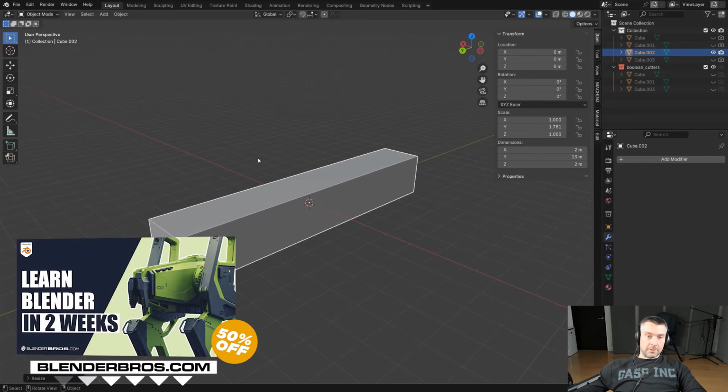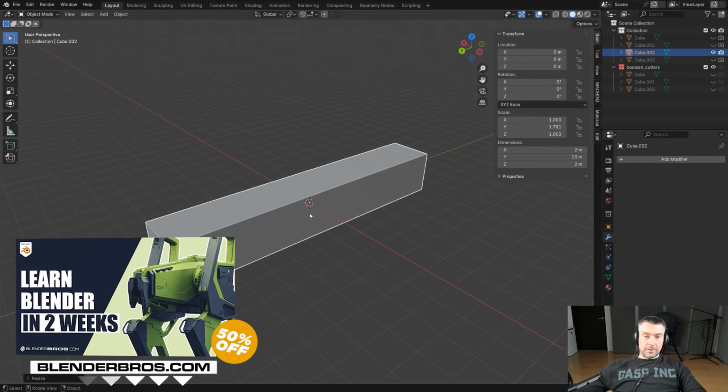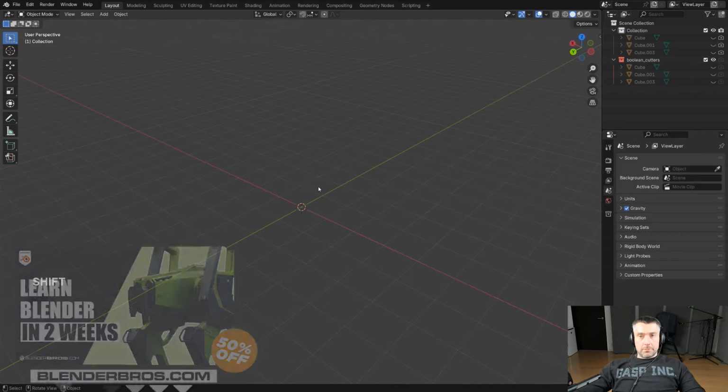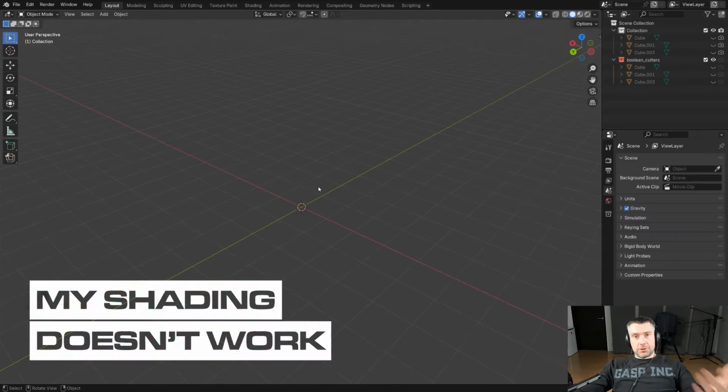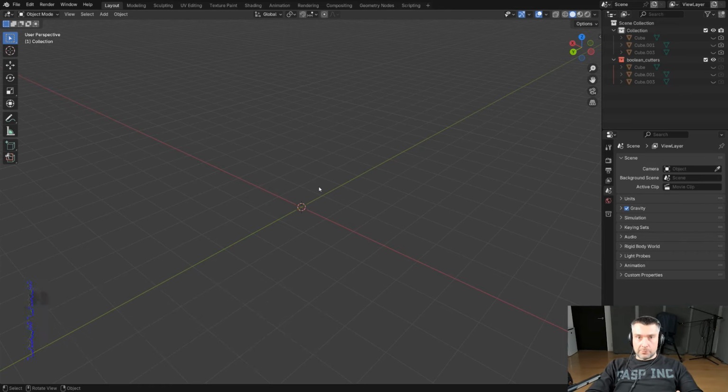But anyway, in vanilla Blender, that's going to be a problem. So remember about that. Another common issue is when the shading goes wonky, and this could be caused by lack of auto smooth, lack of weighted normal modifier, incorrect stack of modifiers, overshooting bevels, flipped geometry, non-manifold geometry, so missing faces, random geometry or random verts in areas you don't need them.